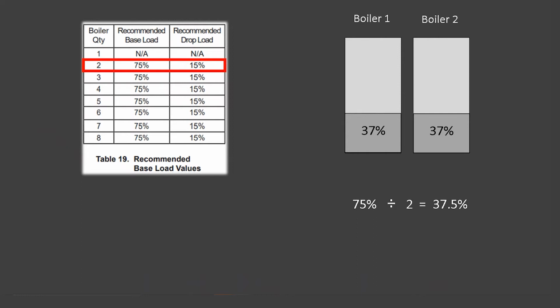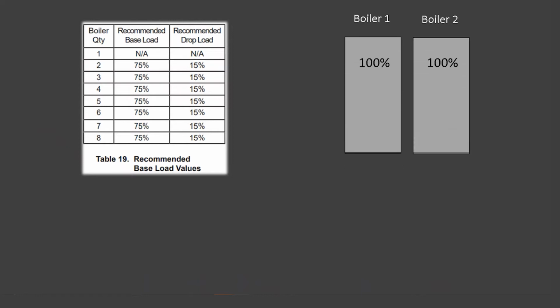It's going to stay there for a couple of seconds for smooth light off, and that will then modulate to 37%. Once they're both at that 37%, they can modulate together. In this example, maybe they go up to 100%. Maybe it's only 80%. Maybe it's 60%. So they'll modulate together in parallel.